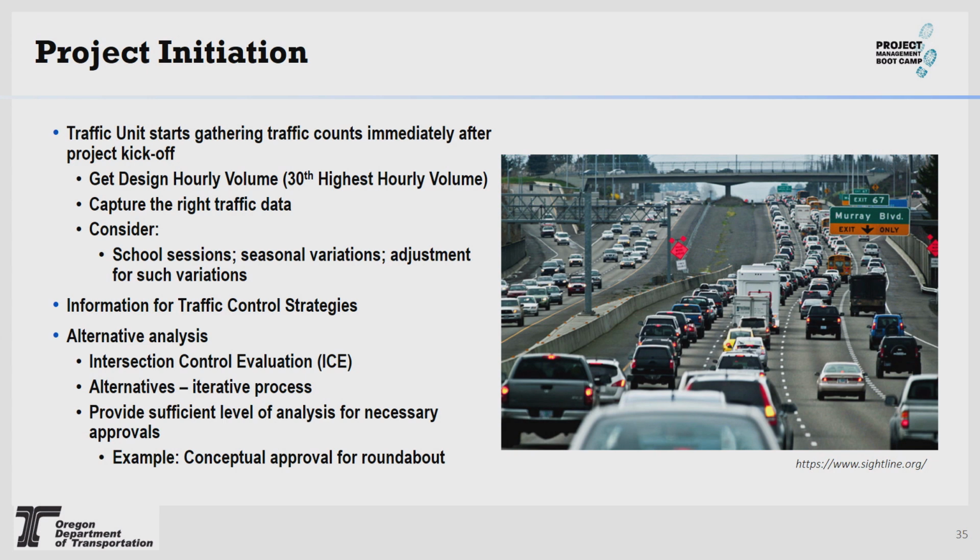If we do not capture the right window, for example, if the project starts in September or October, then we miss the summertime window to capture the right data. In the future analysis, we don't want to do too much seasonal variation adjustment, or work with the wrong data. That's why sometimes we start collecting traffic data even before the project kickoff.